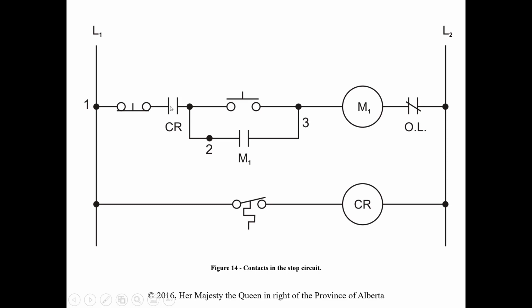And when we have it in the stop circuit, what is it going to affect? Is it going to affect the starting or the stopping of this circuit? Well, we have to look at these contacts in both states. If we look at it in the open state, is it affecting the starting? Well, yeah, if these are open, I cannot start the circuit. So when they're in the stop circuit, in this location, do these contacts affect the starting of this motor? Yes, 100% they do.